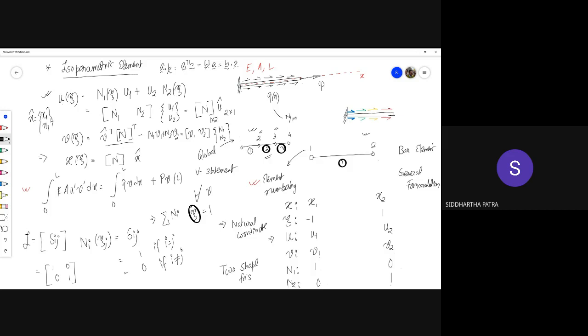And that's where the justification is of something I wrote very sneakily, which is isoparametric element. That means the coordinate as well as the displacement or the degree of freedom are being mapped with the same set of shape functions. So all I'm trying to say here is: N1 x1 plus N2 x2.